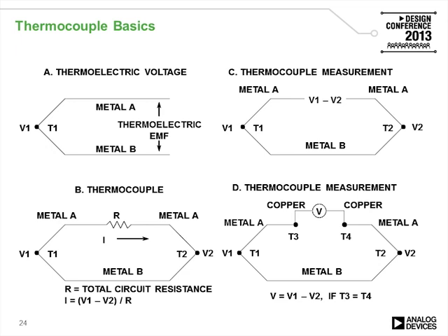At T1, if you increase the temperature, that EMF will go up. The problem is that since it's two different kinds of wires, when you connect it to your measuring instrument, you're also connecting to two even more different kinds of wires. That creates another thermocouple, and if you don't compensate for that effect, you will get errors.